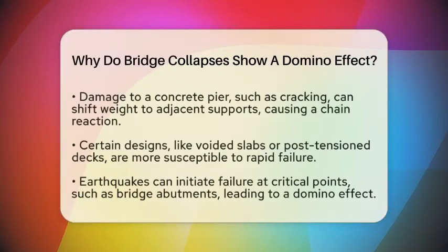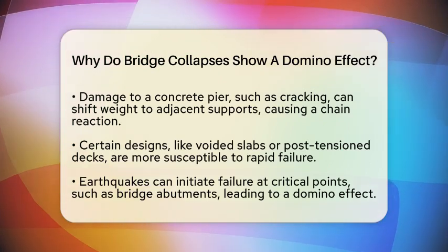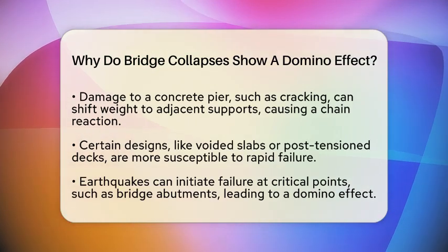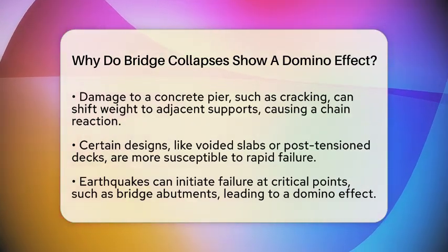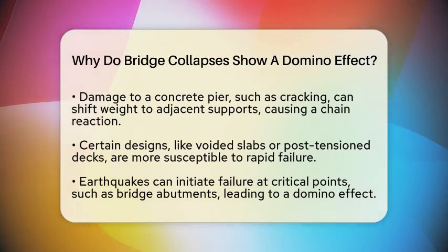Take a bridge with a concrete pier that cracks because of material fatigue or an impact. The load that the pier was supporting now shifts to the adjacent supports or the deck itself. If those parts are already weakened or not designed to handle extra weight, they can give way as well. This process repeats, making the failure spread across the structure like a wave.